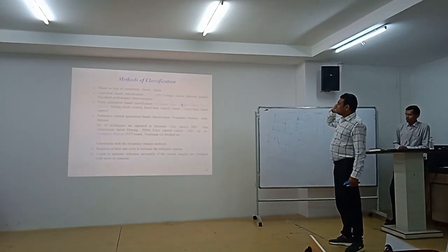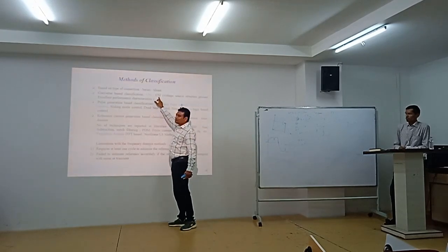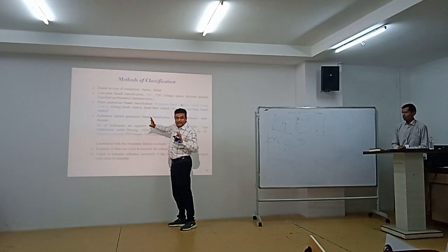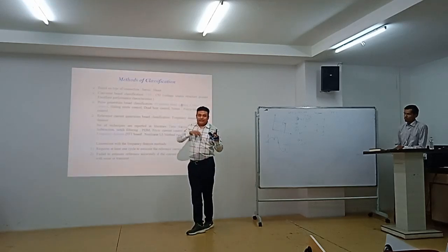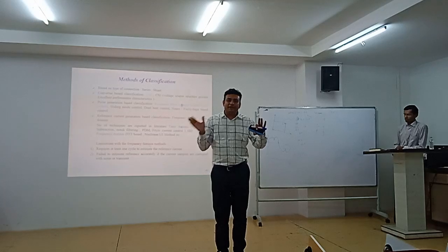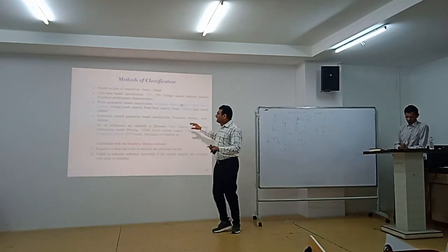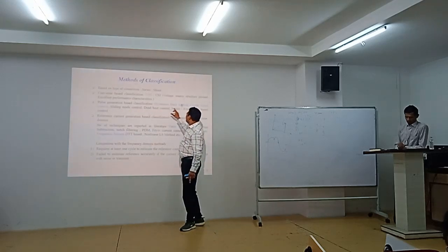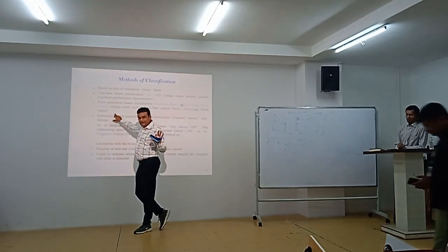These are the classifications. There are a number of classifications. VSI and CSI: voltage source inverter, current source inverter. Then depends on pulse generation. There are so many: hysteresis band control, carrier based control. So either a triangular based, any one carrier is to be taken, and you have to compare the carriers, generation of pulse, and that is given, right? Then sliding mode control, which is latest. Dead beat control, neuro fuzzy logic based control, work has been done on all, right?